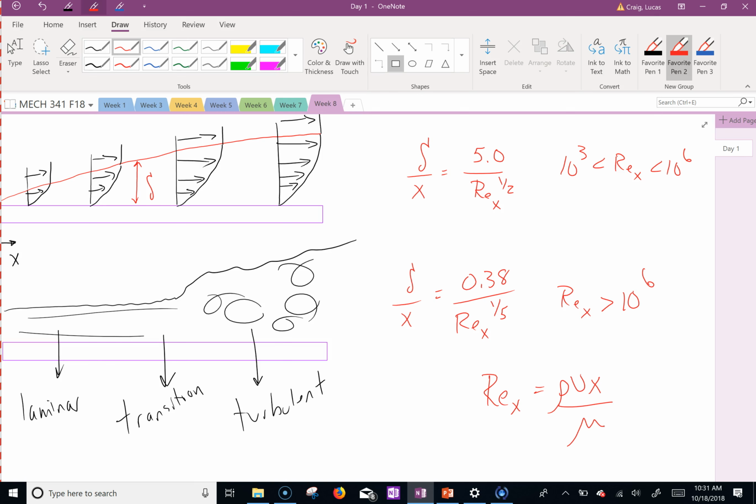The students in heat transfer, did you have those? Remember? Well, you had to find the Reynolds number because you had to determine if it was turbulent or laminar, and then use the specific heat transfer equations for that. What's the purpose of the subscript x on the Reynolds number? It's just meaning this is the direction of x.